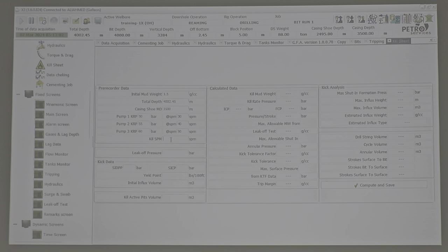So he was the driller working with 60, for example, and the last leak-off test. We know the leak-off test, but he needs not mud weight, he needs bar. So the last leak-off test at casing shoe, for example, 350 bar. Then if the driller has shut in drill pipe, because we close the annulus, shut in drill pipe.